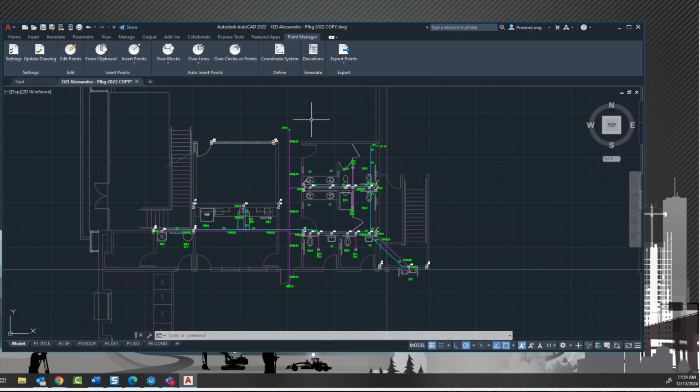So normally you can't lay anything out on a job site to the exact elevation that it might end up, because you're laying out on a deck, either metal deck or wood deck or whatever the layout portion is, right? The elevation of the point in the model doesn't really match what you're actually going to mark in the field. So the elevation is probably not such a big deal, if that makes sense.